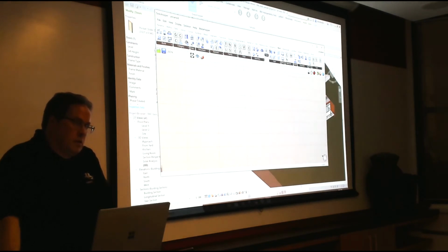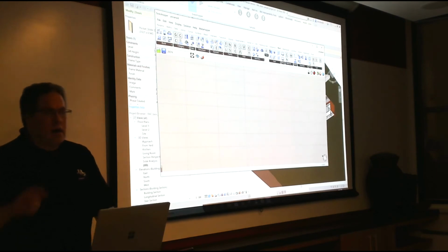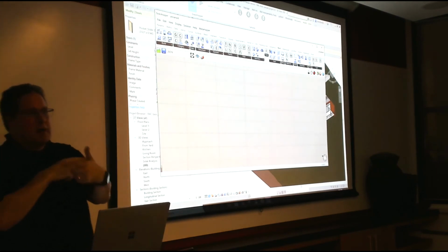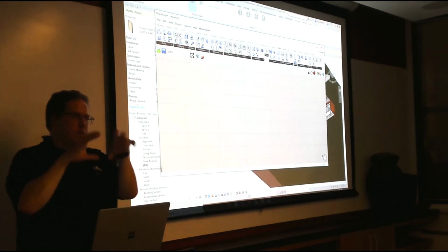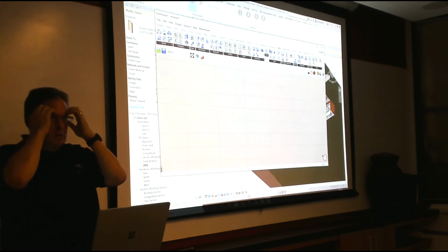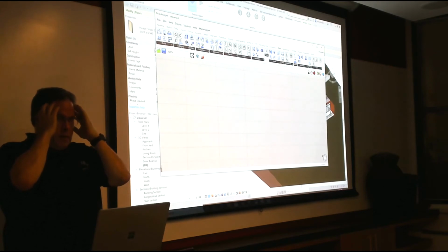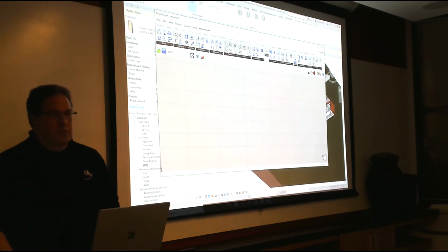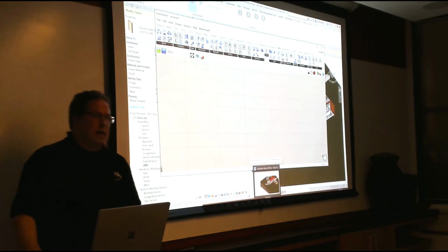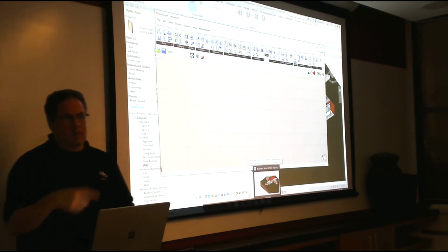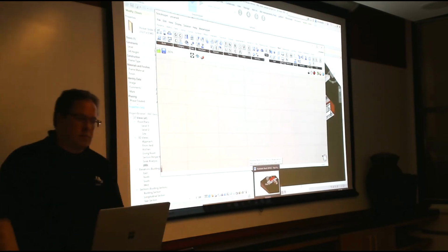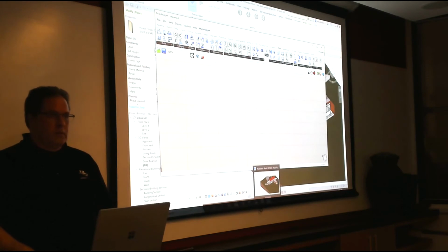So that's what I've been doing, like open in background. Yeah, open it, modify, go back, but you could have that in one Revit. Grasshopper doesn't have to close. Right. So that open in background is like a Python process for me right now. We'd have to have you talk to Hassan about what's possible and not possible through the SDK. There are some timing issues there with adaptive components. That's why I've had to separate into two separate Grasshopper scripts.